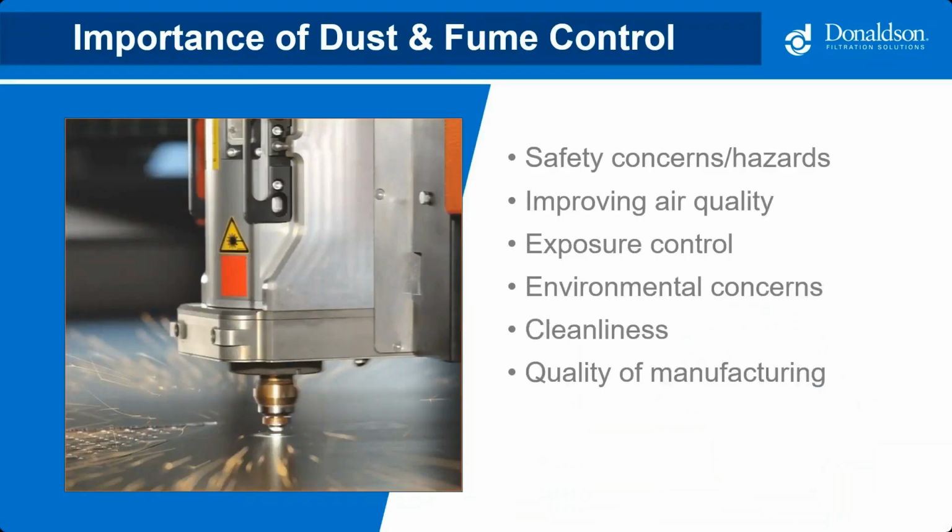So as mentioned, there's a lot of important reasons to control dust and fume generated during laser cutting operations. Obviously, the safety concerns and hazards I just mentioned, improving the overall air quality for employees, exposure control, so really reducing the potential dust in the breathing zones where the workers operate, environmental concerns such as EPA standards for outdoor exhausted environmental air quality and outlet emission requirements, cleanliness concerns, the overall cleanliness of the facility, and quality of manufacturing, because that dust can interfere with the laser cutting performance.